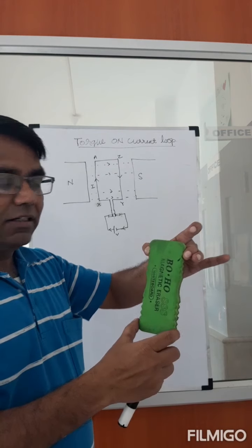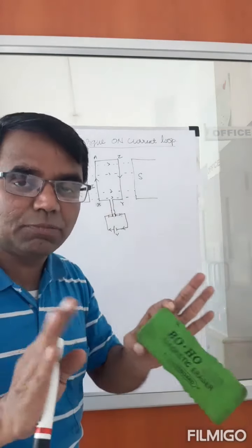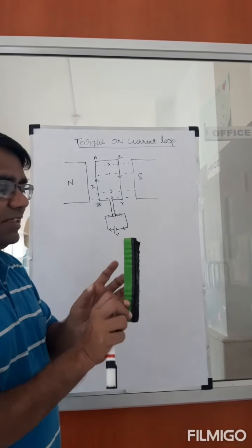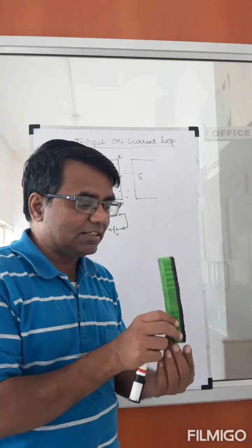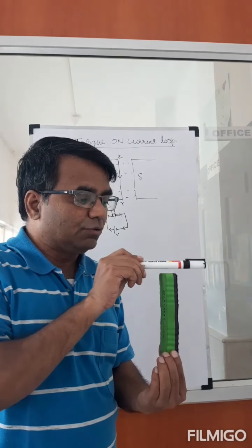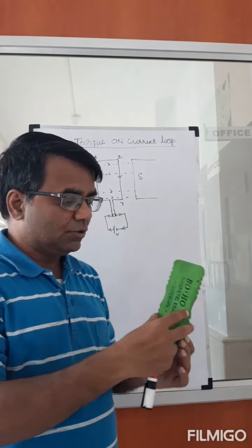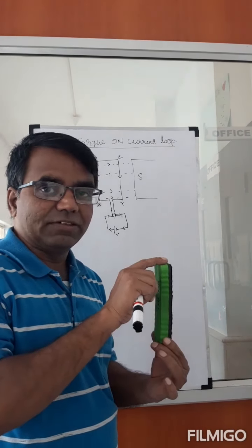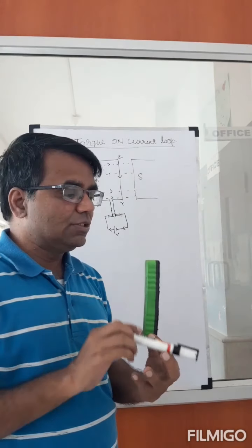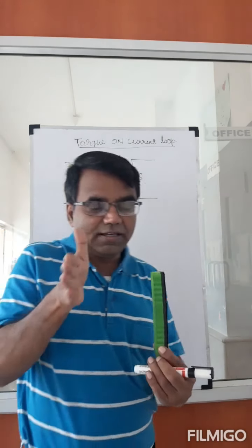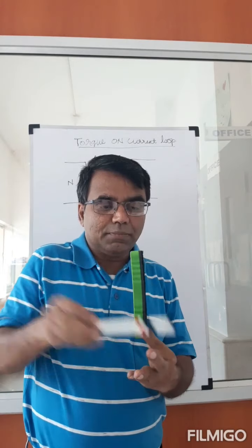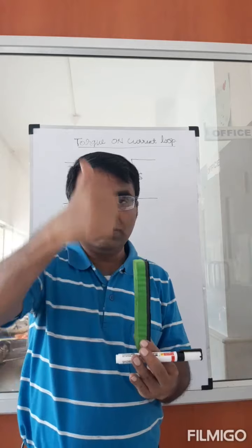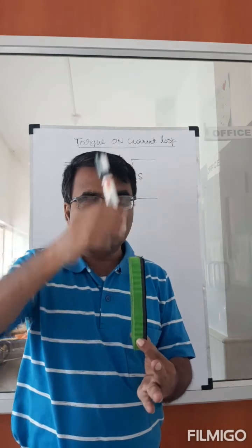Let's talk about the direction of those forces. Right now, let's say this is in this position. Let's rotate it. Let us say it has come here. B is in this direction. So this is A, current has gone there, and then it is coming like this. So current is in this direction. I, for this conductor, is in this direction. B, as I said, is in this direction. I L cross B will give me this direction. So force will be acting upwards.